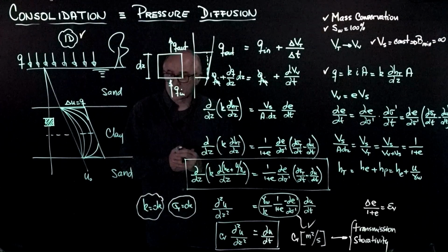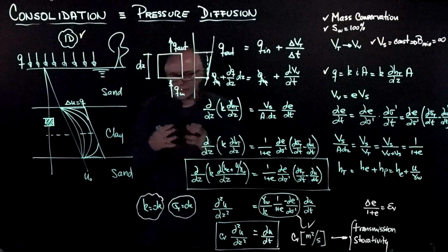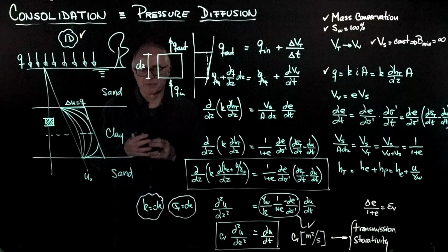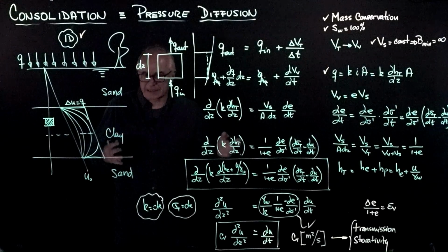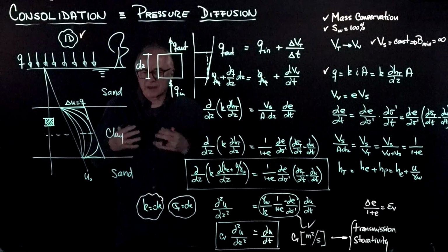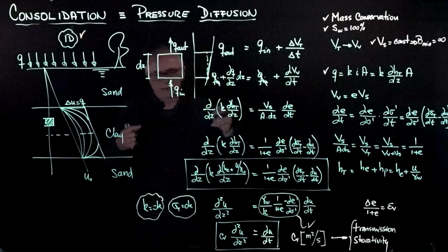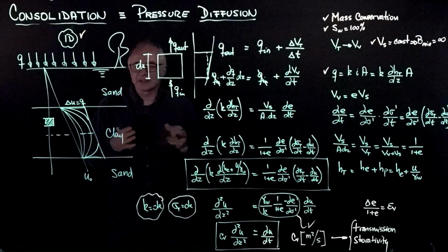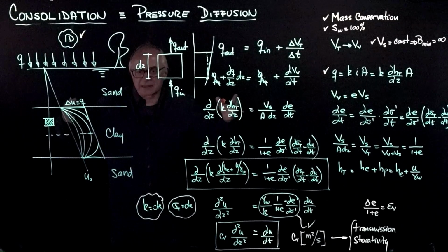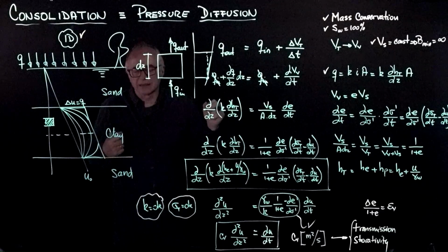One final observation. For an advective process, what we were talking about in previous lectures on hydraulic conductivity, permittivity, steady-state seepage, we know the velocity of fluid flow from Darcy, which is K times i. So the time scale is the size of our problem, let's say a certain length L, divided by the velocity, Ki.